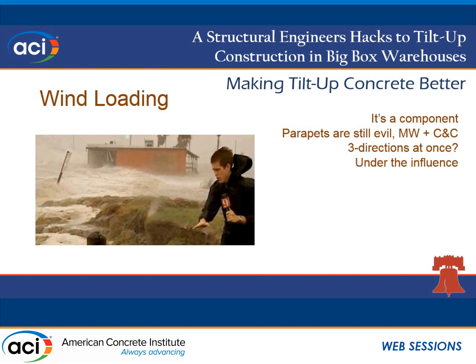You can have a panel that's 1,500 square feet, but when you're designing the elements within the panel, when you've got a jamb on the left side of the panel, it's affected by the loading on that side. It doesn't get affected by the main wind force where you can average it over a larger area. So no matter what Factory Mutual says, a panel is a component. Now this can make about a 30% difference in your wind loads, so I'm saying that this is what I would do.